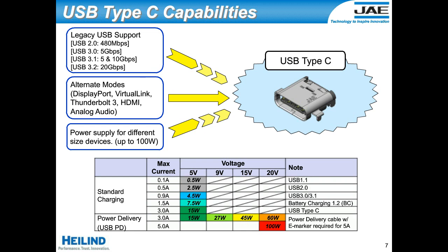The much slower USB 2.0 and 1.1 signals are also obviously supported in the USB Type-C connector. These original D+ and D- data pair contacts still exist inside of the USB Type-C, so it can support all these previous generations from low speed all the way up to the latest SuperSpeed Plus data rates.